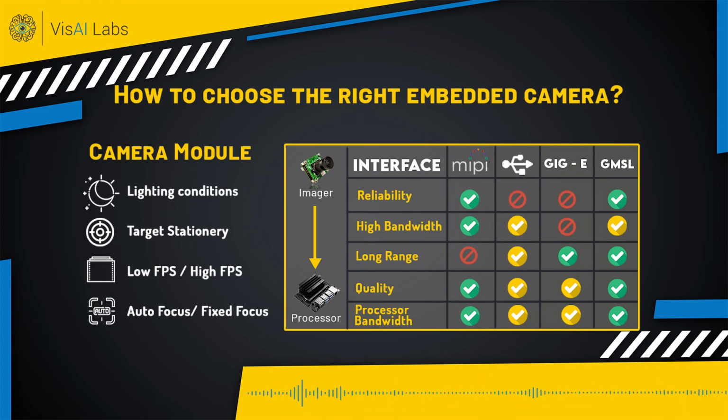Also, if the use case requires a color camera, make sure to choose the camera module with an image signal processor. The image signal processor is the one which is responsible for auto functions. Adapting to different lighting and perfect color reproduction is a key thing, and without an image signal processor, it is going to be really tough. So consider these points before choosing the camera module.